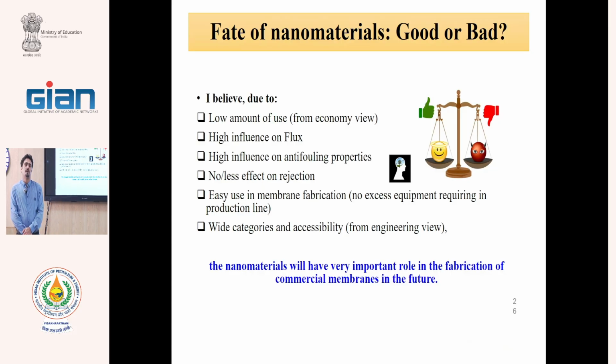The uniform coating of nanoparticle is very important. For example, in a filtration method, when we filter the nanoparticles through the membrane, if the pore size of the membrane is different, one pore big, one pore small, then most of the solution will go through the big pore, and most nanoparticles will coat the big pore surface, and we will not have uniformity.